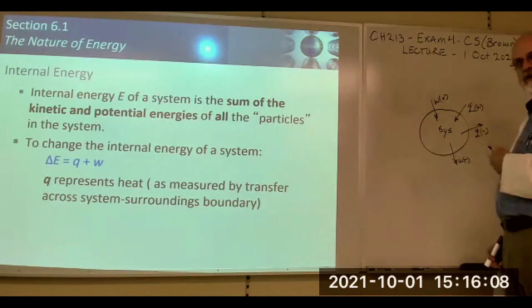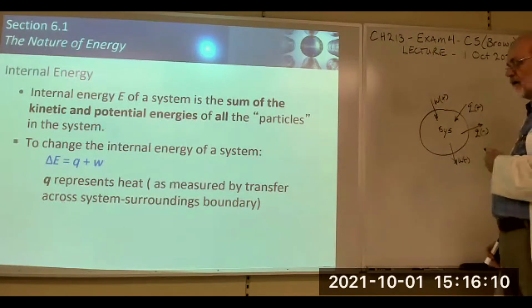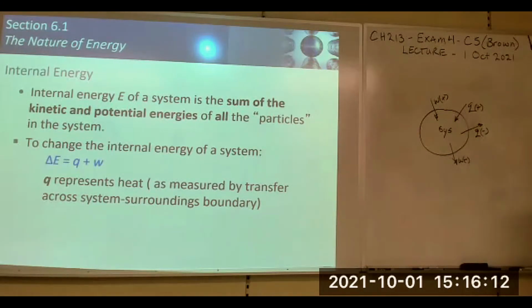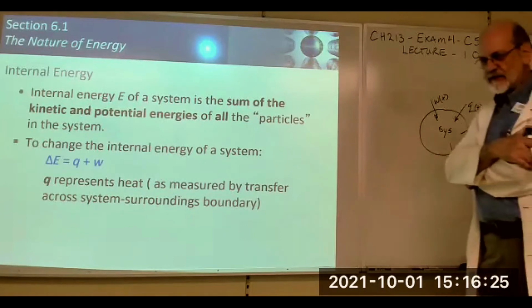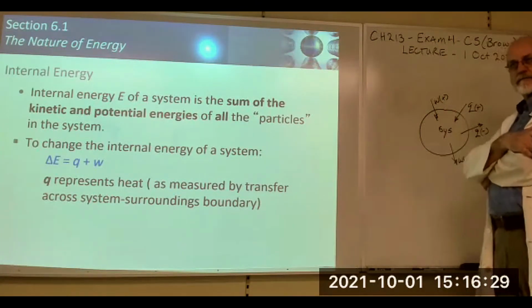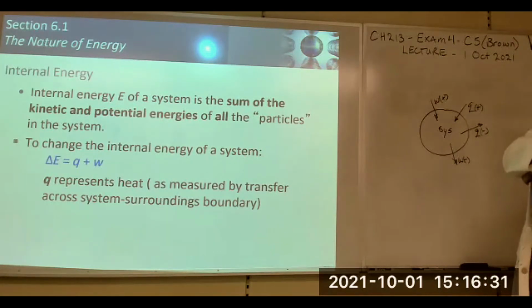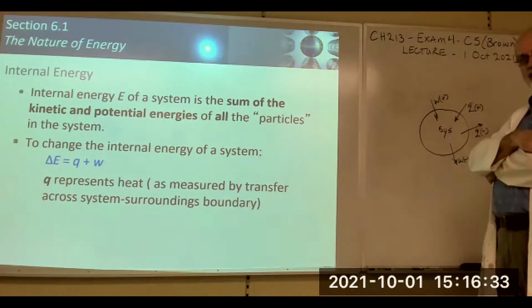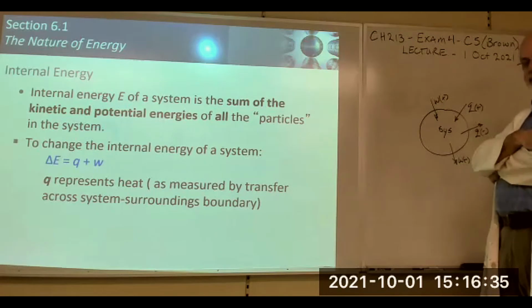If it gained too much heat, yeah, I guess you'd have to define the system. Some systems are pretty good at holding heat. For instance, in power plants, that's why the nuclear power plants in the US have always been pressurized water systems, because you can heat water to a very high temperature as long as you keep it under pressure. Right? If you don't, then it'll flash into steam.